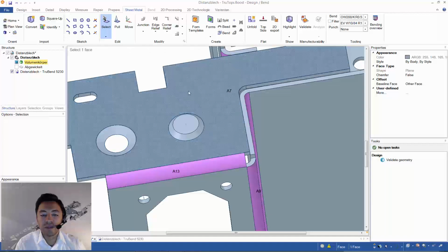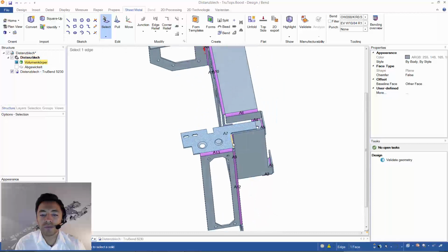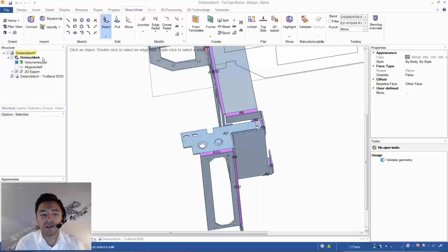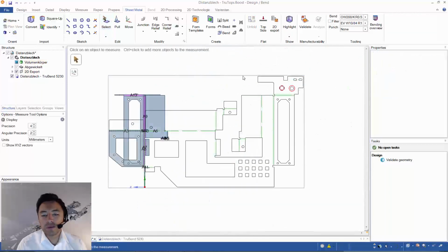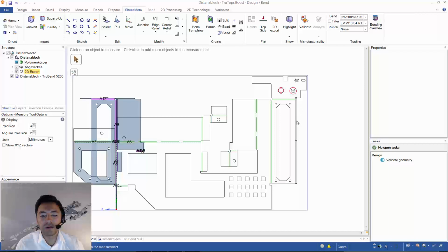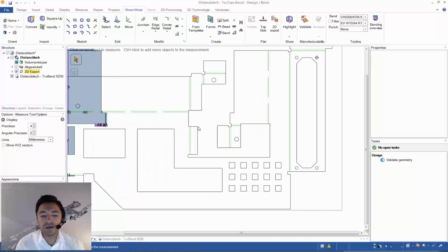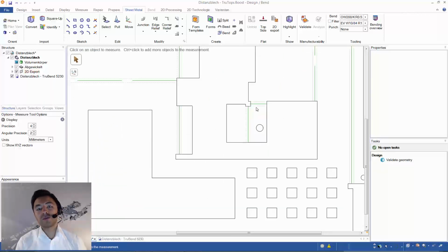All right, that special feature of exporting 2D geometries, which I have mentioned before, is right here. So if you flat out, you see within the structure tree, the 2D export is inserted. Within the 2D export we see what is being marked and what's not being marked. The layout lines are just deactivated. Otherwise, that 2D export will be the base for your laser program.